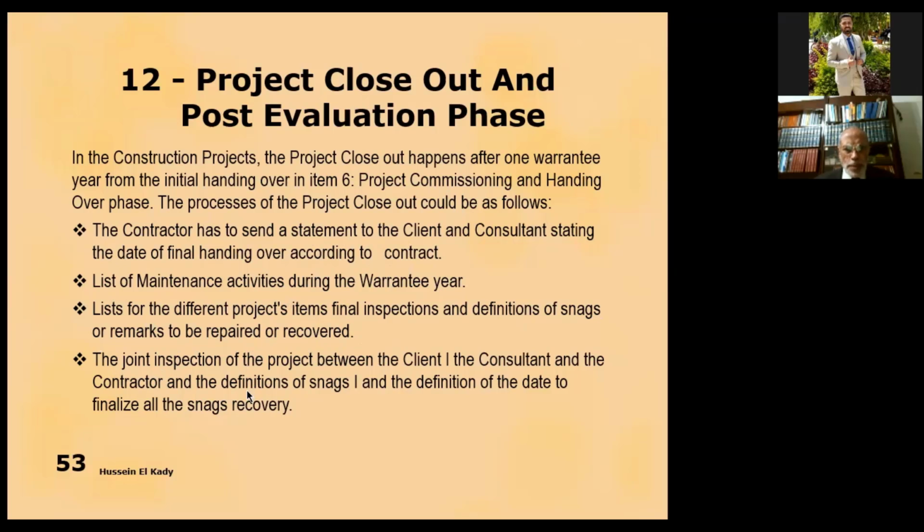The joint inspection of the project between the client, the consultant and the contractor, and the definition of snags and the date to finalize all the snags recovery. Then, if we take the snags, we have to make a schedule or a plan for when they will be finalized. It mustn't consume so much time, let us say a couple of weeks maximum to finalize it and all the issues of the closing out.